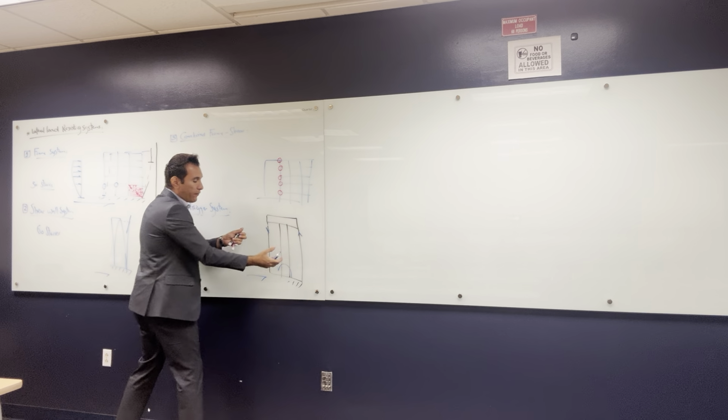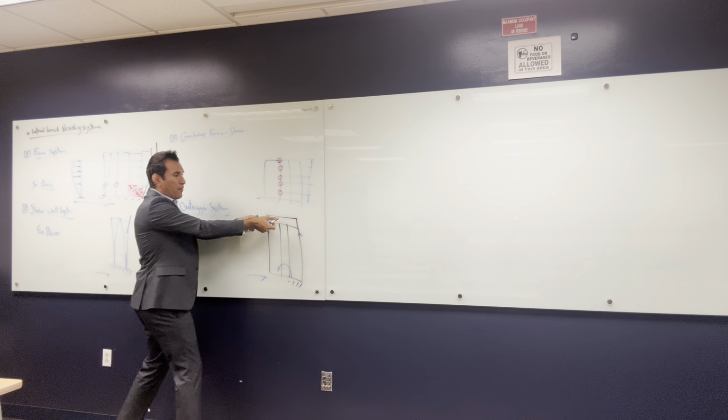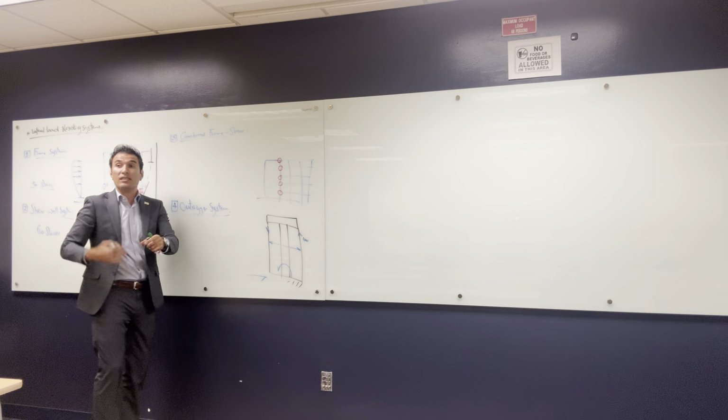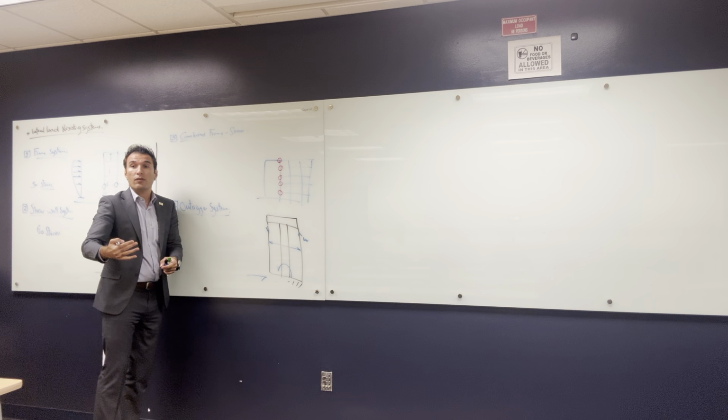The shear wall wants to go this way, but this outrigger, this cap, is making a counter force because of the arm of the moment between these two columns. And let's say if this has a 10 or maybe 100-ton reaction, this 100 ton is gonna be multiplied by the arm of moment that is really huge, the complete width of the building. So that's increasing the lateral resisting force of the system.